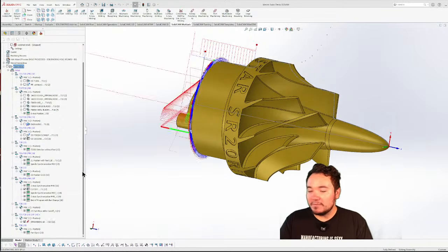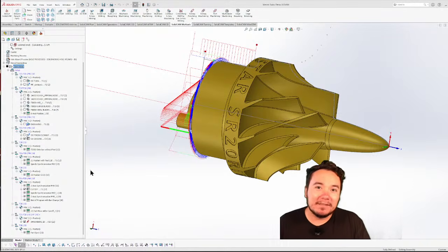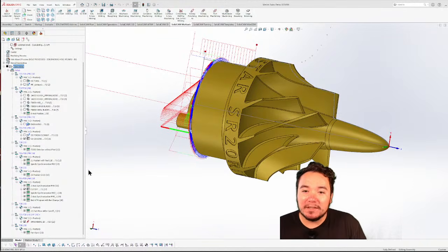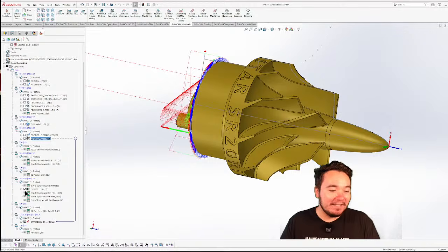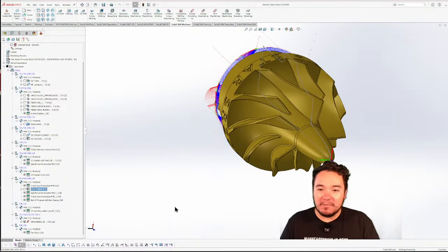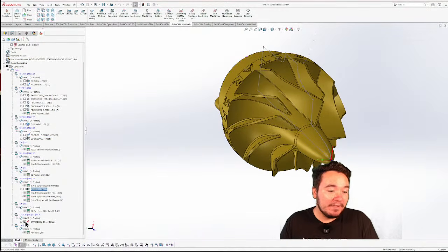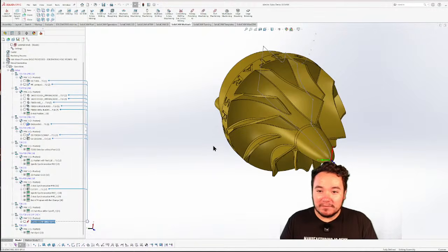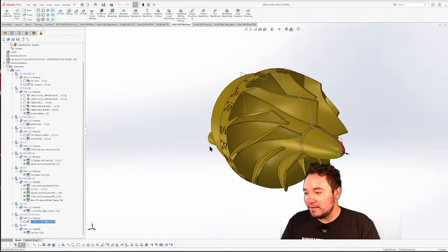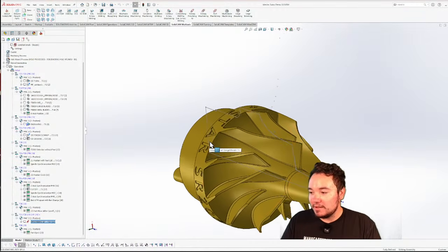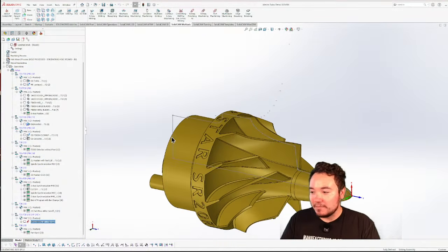Yeah, we just used it just because it was easy to get ball end mills. I do see a lot of people using the lollipop end mills, but we just did it out of sake of cheap and easy to program with. The program looked fine with the ball end mill, and that's just what we decided to use on it. But I have seen a bunch of people use the lollipop style end mills. So you can go either way. The one of choice definitely is probably going to be the lollipop.